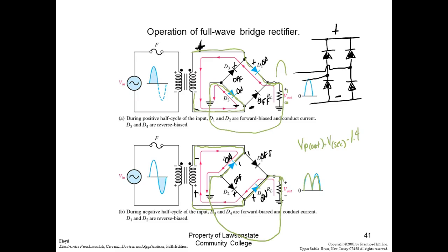That's why your car alternator is regulated. So it gives us out, when the car's running, a pretty constant voltage. Like I said, go out there and take your voltmeter and hook it up to your battery and turn your lights on, and you'll see the voltage of the battery drop down. Crank that sucker up, and all of a sudden you're getting about 14.3 volts, and you turn your lights on, you turn your air conditioner on, you raise your windows, and it's going to maintain that because it's regulated.